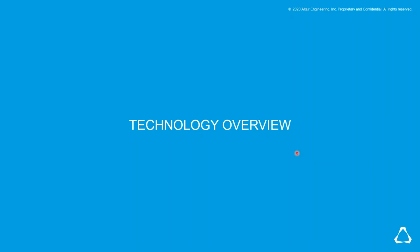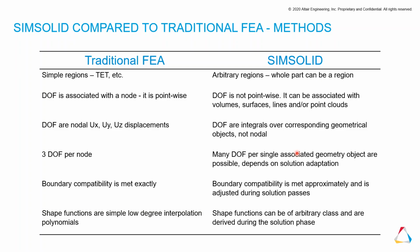Now, just a little bit of technical background on how SimSolid works, comparing it to traditional finite element analysis. Your traditional FEA will use elements, so probably you create tetra elements, quad elements, hexa elements. We break down a part into smaller elements represented by tetra, hexa, or quads and triangles and so on. But in SimSolid, we don't break them down into such small elements.